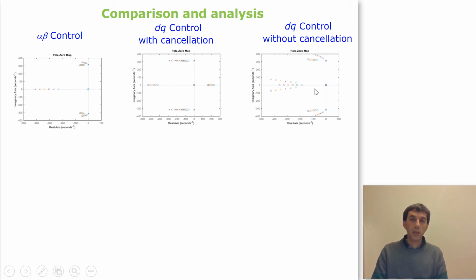So here we can see how by changing the gains of the regulators, we can make the system more stable or more unstable, by checking, for instance, how close we locate the transient response poles to the imaginary axis. You know that this is the unstable area. So here we see the tendencies.